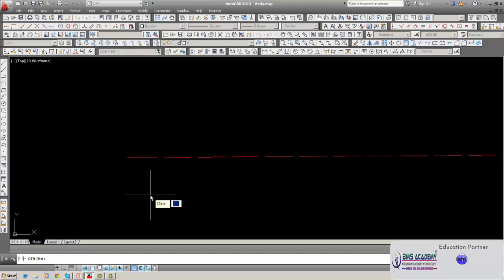So what we are going to do is increase the size by the LT scale by 100. It is 6 and we increase it by 100. So 6 becomes LT scale 100. If you make the LT scale 100, then in the actual drawing the distance will be 600. But when you print it, the distance will be just 6 mm on the printing paper.